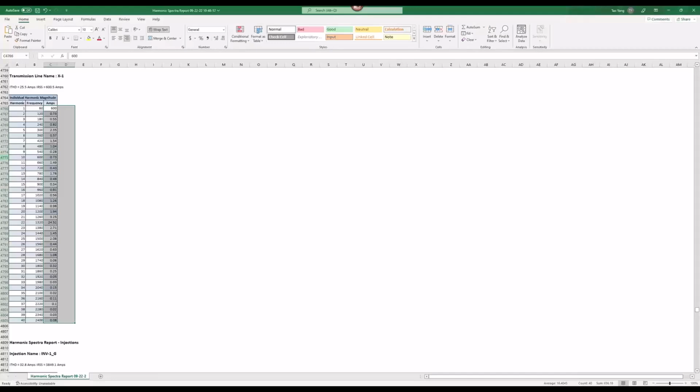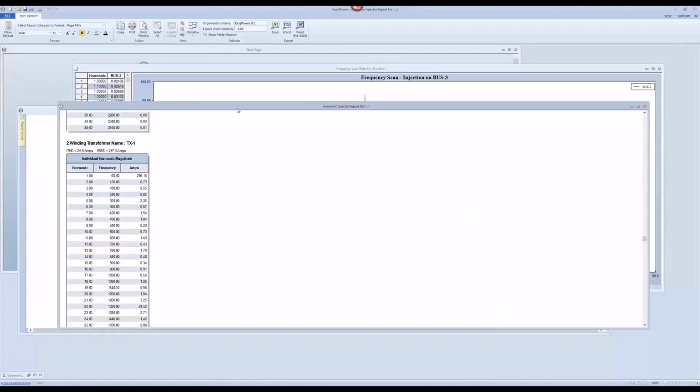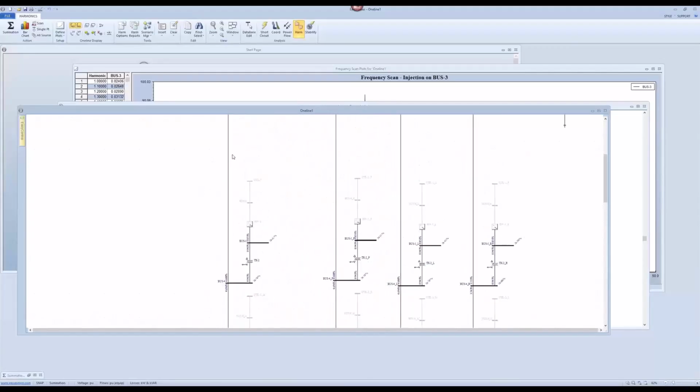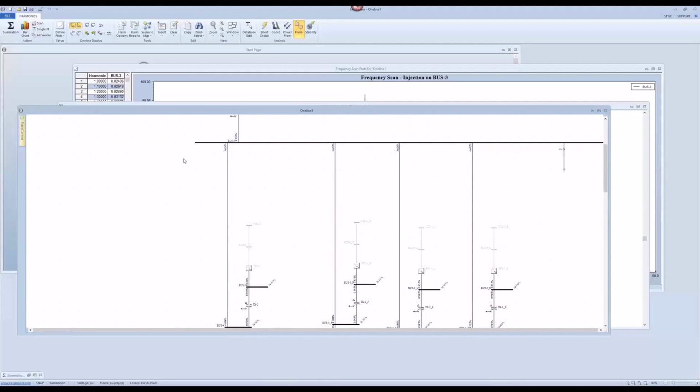Do studies need a detailed model of the collector and inverters, or can you get by with an equivalent collector and inverter model? The answer is you have to model every inverter specifically. What we're doing is a harmonic study. It's not a short circuit study or power flow study or stability study. So we have to model the power plant in detail. The reason is very simple and straightforward. Go back to EasyPower, and you will see that every cable registers capacitance. So it behaves at two ends like a voltage booster or a current path to the ground, right?